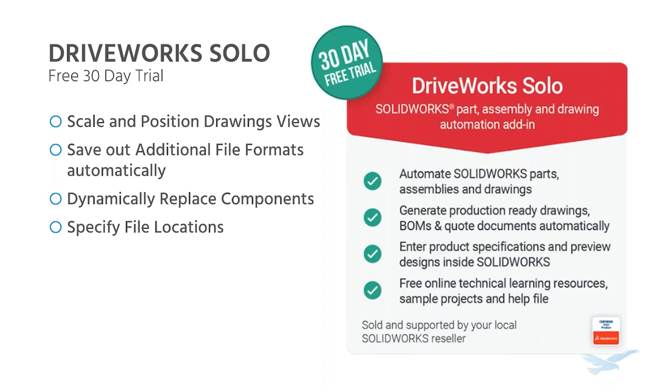We can also swap in dynamically, so swapping in different components very, very easily. And inside DriveWorks Solo, we can save your files into the exact location that you want. So DriveWorks Express saves all of your generated files in the same location as the files that you capture. Whereas DriveWorks Solo, using the same rules syntax that Ronnie showed us, you can build file paths to save them where you need them, whether that be on your machine or on a network location.